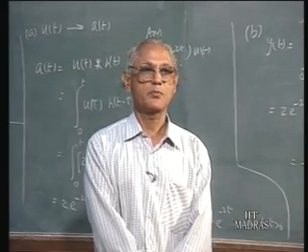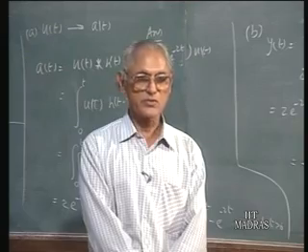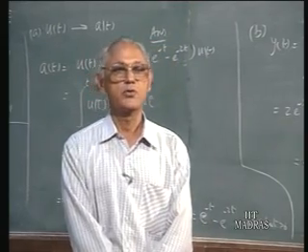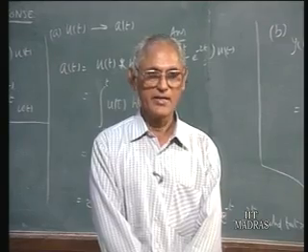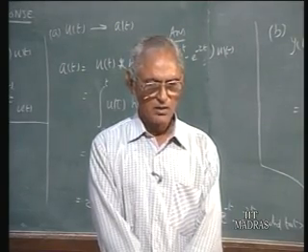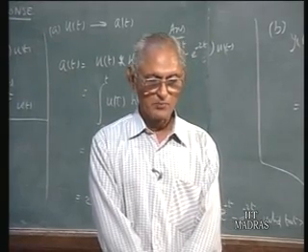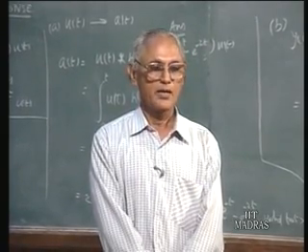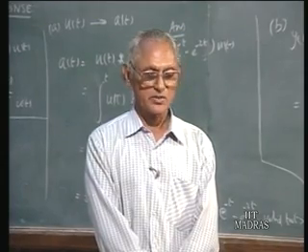The differential equation approach, the system function approach, both as a function of s and as a function of j omega, or in time domain using either the impulse response or the step response, sometimes called indicial response. The step response is also called indicial response. Some of these techniques we will return to later when we are talking about Laplace transformation techniques. And so we will close our discussion of the introductory system concepts at this stage.